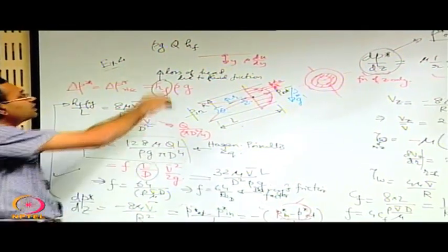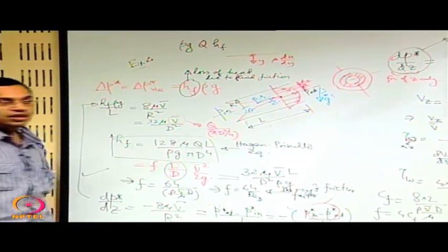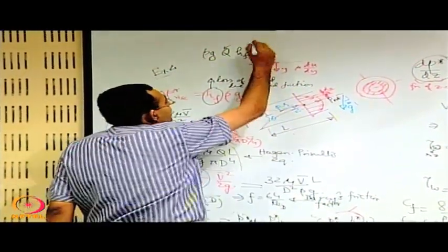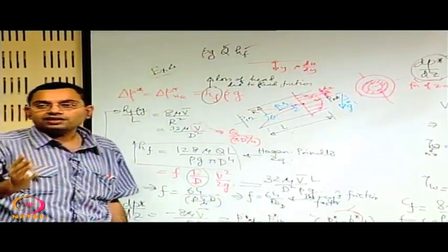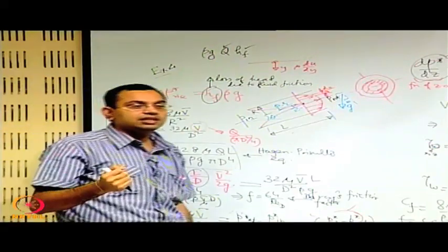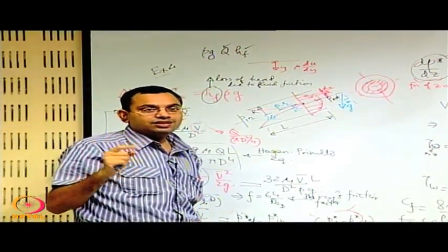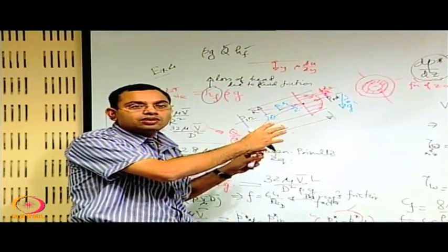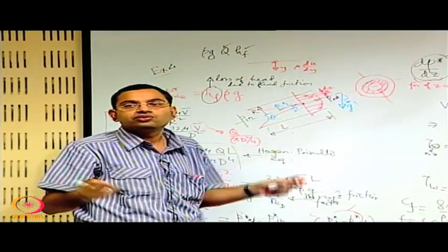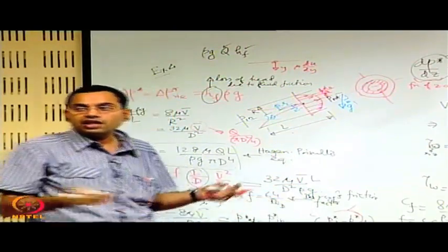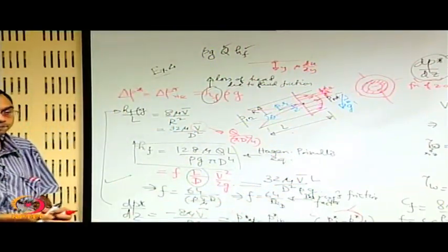This is a unit of power. If you know the flow rate and the head that the pump has to supply, then you know the power of the pump necessary. So a very basic elemental mathematical work is necessary even for a very crude design work, which is there in the day to day life of fluid mechanics, like flow through pipes.